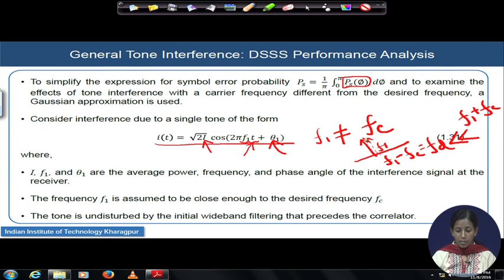Another consideration is that when the signal is received by the receiver antenna, as for all kinds of receiving antenna, the received signal is passed by a wideband filter, then amplified, passed to the low noise amplifier, and then fed to the matched filter.